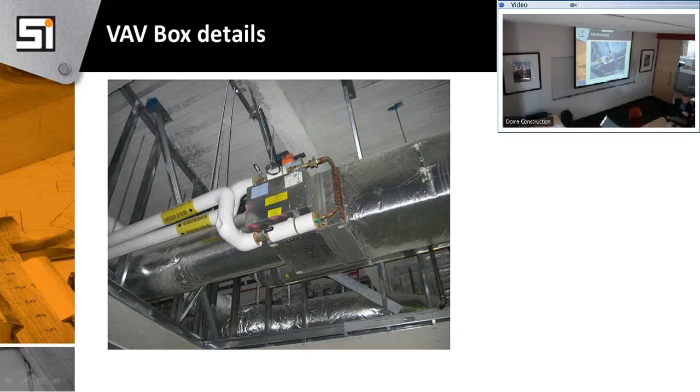Someone moved the speaker, the microphone. Valve opens up. Well, it depends. It depends on the airflow of the room versus the heat setting you're looking for. It may do one of two things. It could throttle the air a little bit and open the valve a little bit. If the air is not coming through enough, it'll open the heating valve a little bit more. But it's all working in concert with the air flowing through it versus the temperature setting.